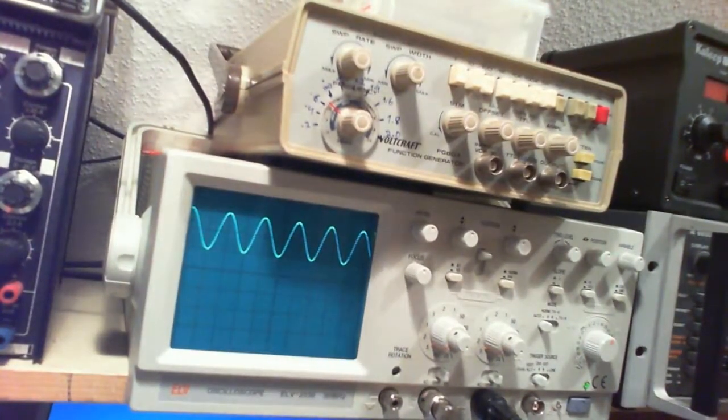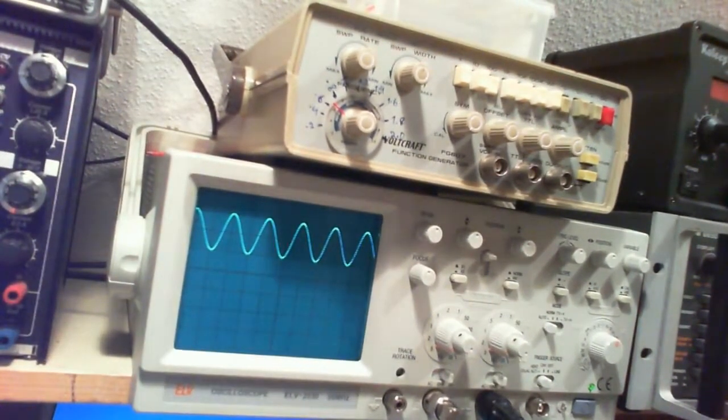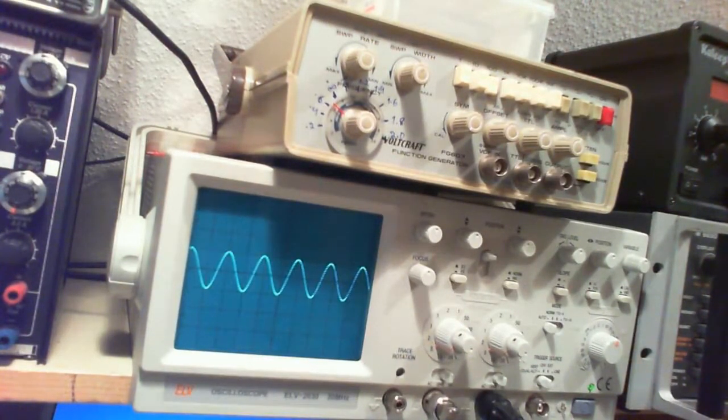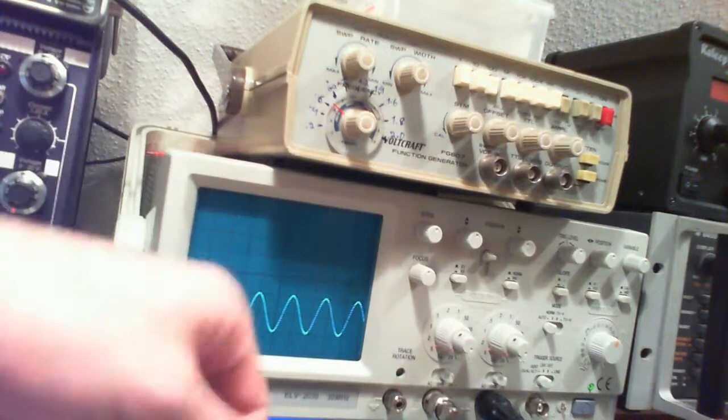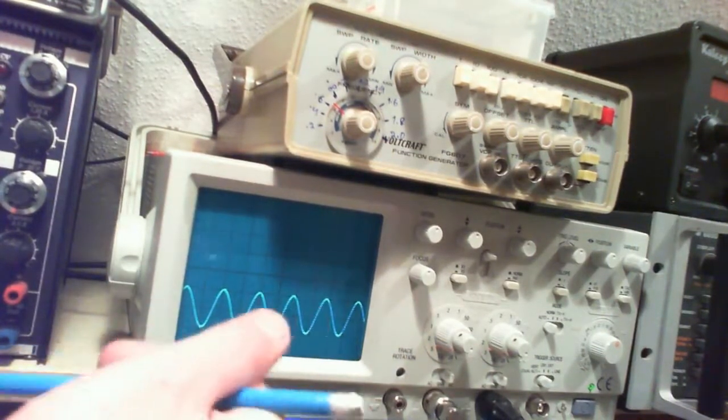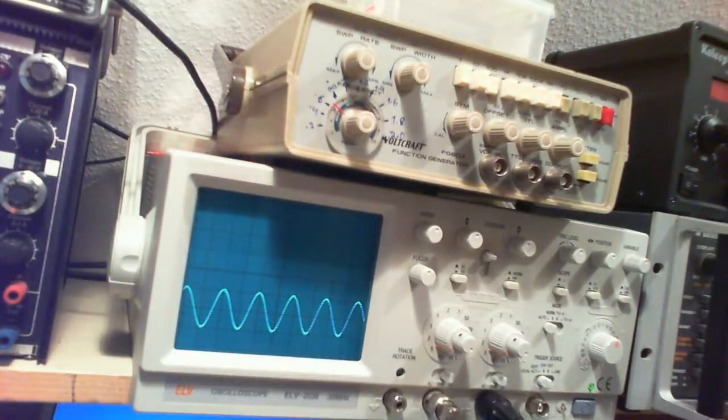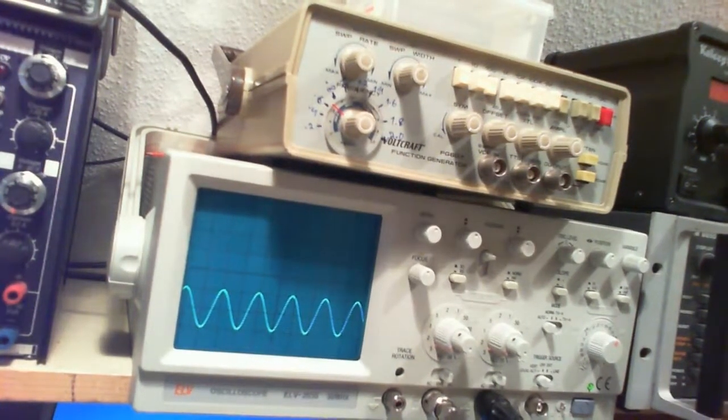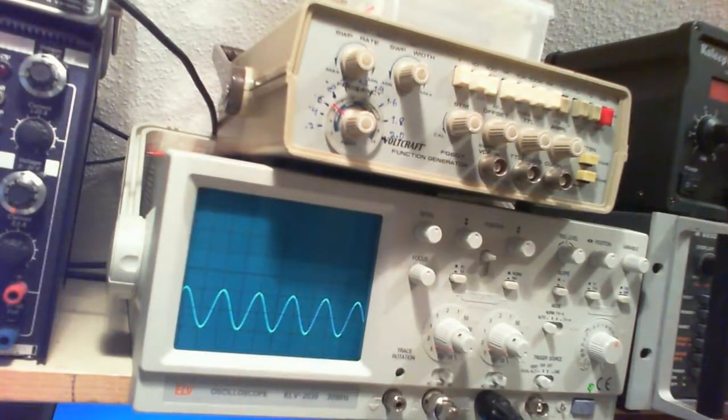So now my DC offset is positive 10 volts DC actually. And if I move the DC offset to negative, I will get a negative. Now it's off, and negative, you see, I move down here. That means that now the DC offset has a negative 10 volts. So that's basically your DC offset. And if you want to actually measure this DC offset on, for example, a multimeter, you can do that.